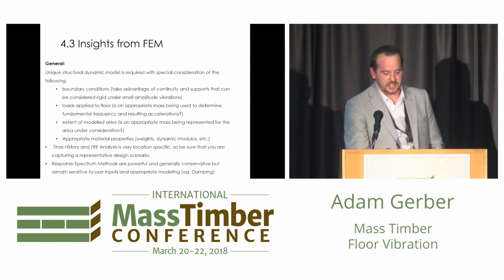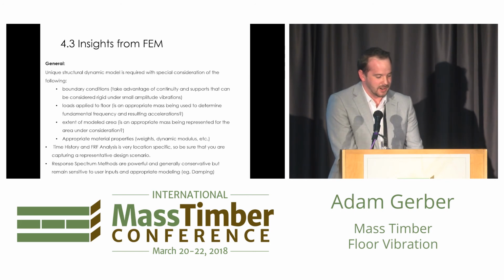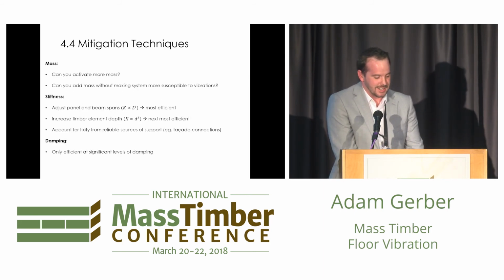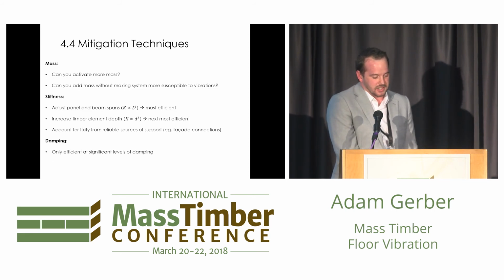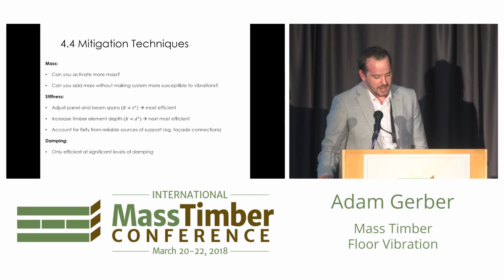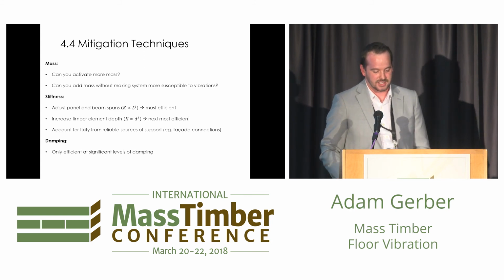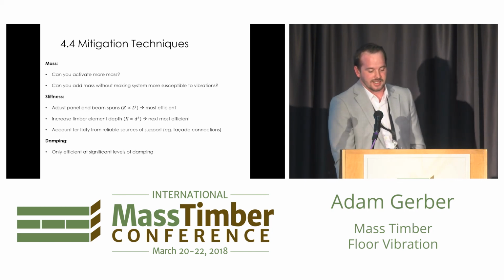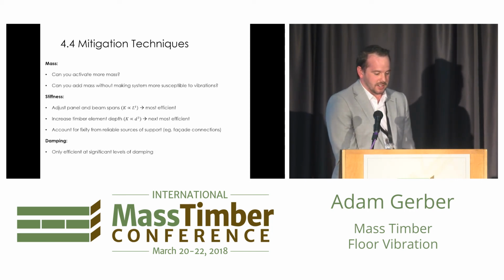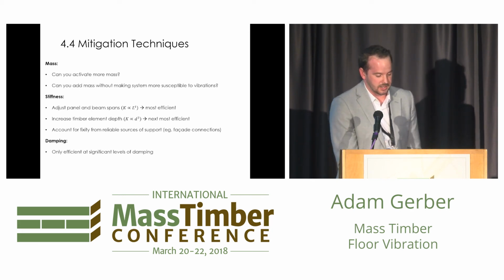So I think I'm pretty much out of time, so I'm not going to spend any more on the, I've got a few insights from finite element modeling, and there's a lot out there as well. Basically, a few mitigation techniques. If you can activate more mass, it's your friend. If you can add mass without making the system worse by basically making it composite, that can be your friend as well, because you're getting the same frequency but more mass, so you're just reducing your accelerations.